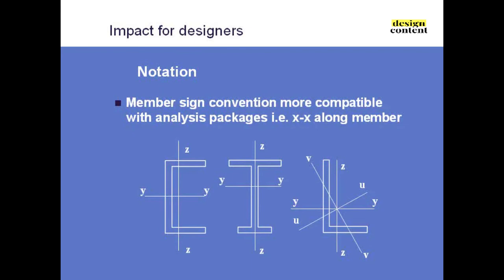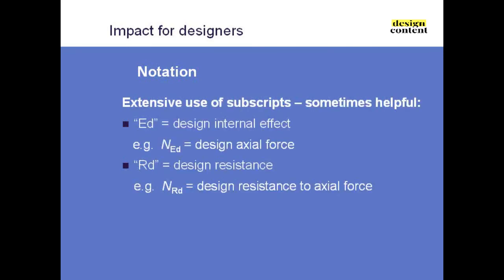You'll also find over the next few days that the Eurocodes use subscripts a lot. And you just have to get to like them. It's a bit like learning a language again. They do enable you to work out what something means with a bit of practice. So a simple example here: ED is used as a subscript for the design internal effect. Basically means effect design in a member. So if you see NED, that's the design axial force within a member.